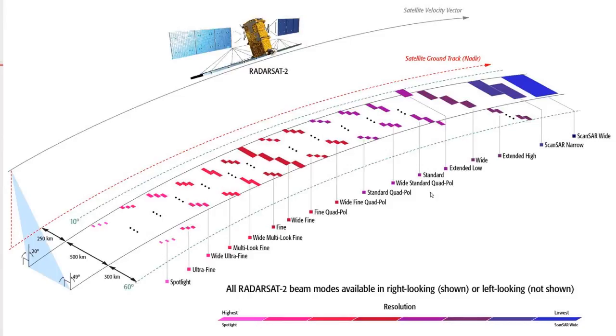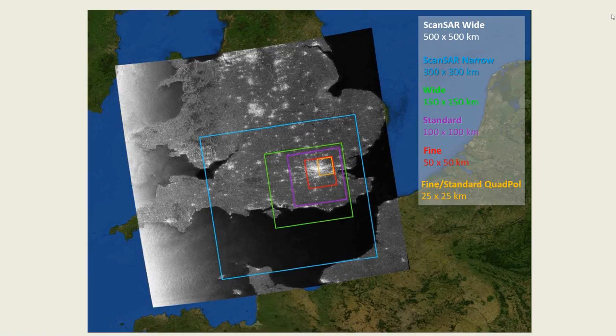When really wide area coverage is most critical, and when you're looking at a big oil spill, that can definitely be the case. We get a lot of use out of our ScanSAR modes in looking at oil spills and being able to detect the extent of oil spills. For flooding, many national disaster management agencies will use our standard mode, which provides 25 meter resolution over a 100 kilometer swath width. That provides pretty good resolution while still looking at a very large area, and is one of those modes that's just been standardized over time.